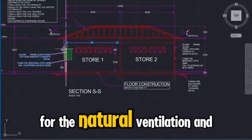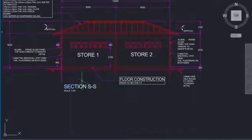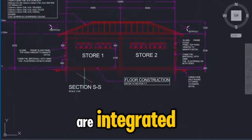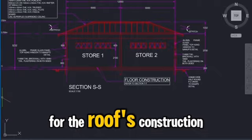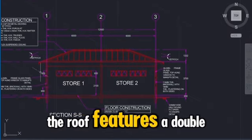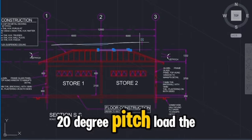For the natural ventilation and lighting, top hung aluminium frame glass windows are integrated. For the roof construction, the roof features a double pitch design at a 20-degree pitch.